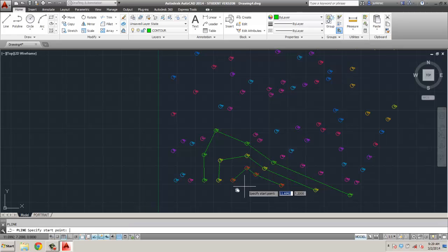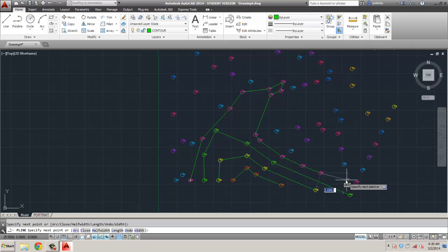This is just kind of, I won't call it brainless work, but you can zoom out. If you zoom out, you can still see the X on there, so it makes it easy for you to identify when you're right on the center of that point. So if you had a total station, it might give you a file like this, which is nothing more than XY coordinates with elevation numbers on it.